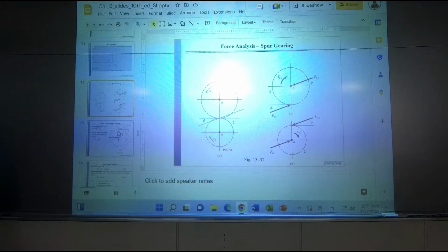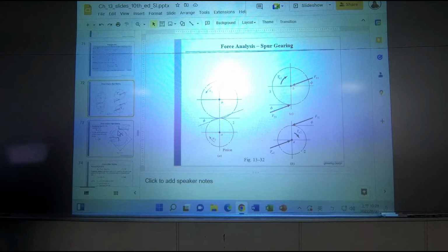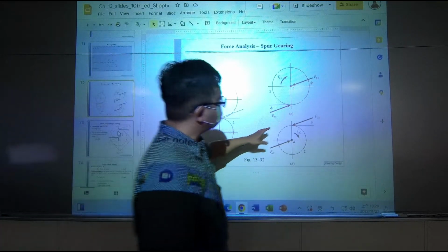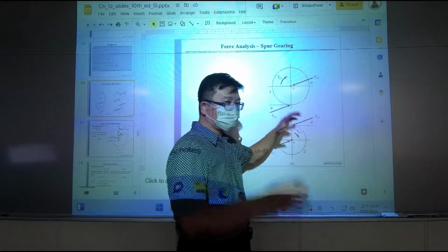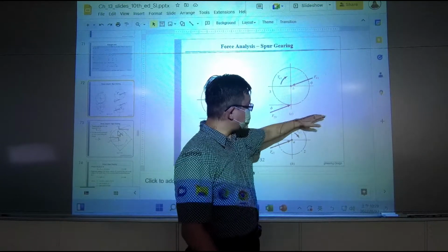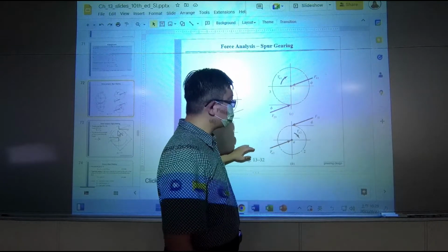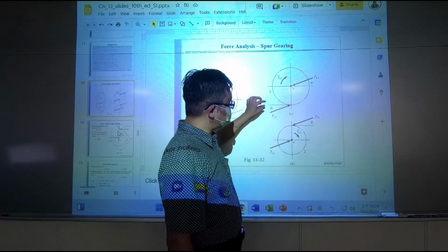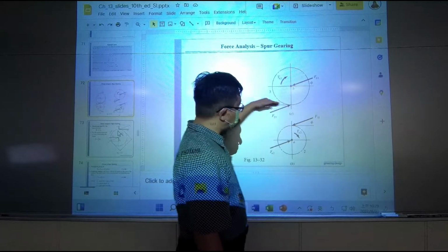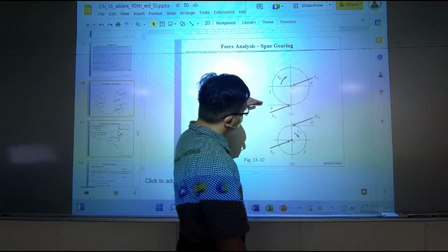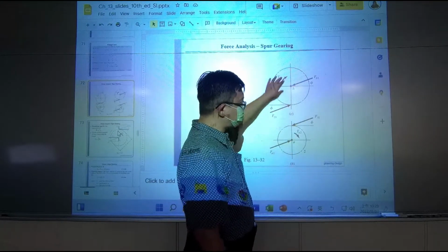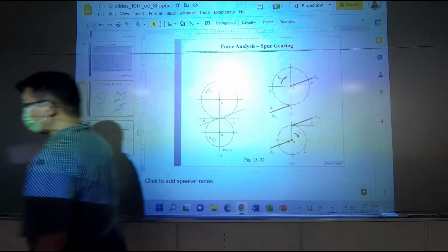Last time we talked about spur gears. They face each other, and the transmission of loads between the teeth from both sides follows a tilting line, which has a pressure angle against this tangent, you can say tangent surface between the two gears. Okay, so that's pressure angle.